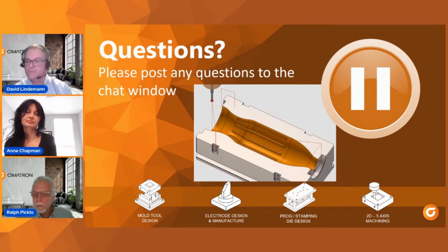We got another question. After they're measuring, it adjusts the tool radius difference, and do you need to run the program again, or does it automatically run the program again? No, it doesn't automatically run it again. What we're doing is adjusting the finish cut on it. That's the best practice that we're doing on that.